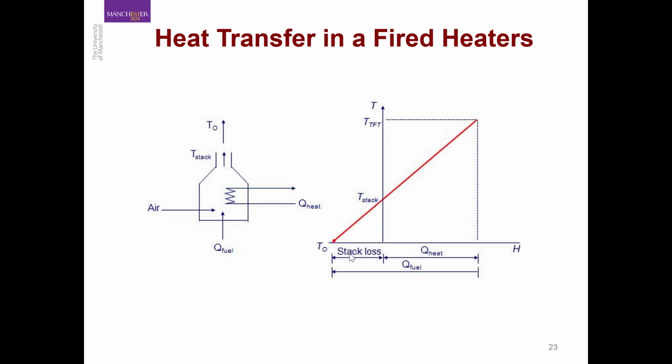It is the heat from the flue gas that we cannot use to heat our process, or we don't require. But actually it is not necessarily a loss, because we can use some part of the heat from this flue gas in the stack either to heat the fuel or preheat our air. As such we can increase the supply temperature of the flue gas.